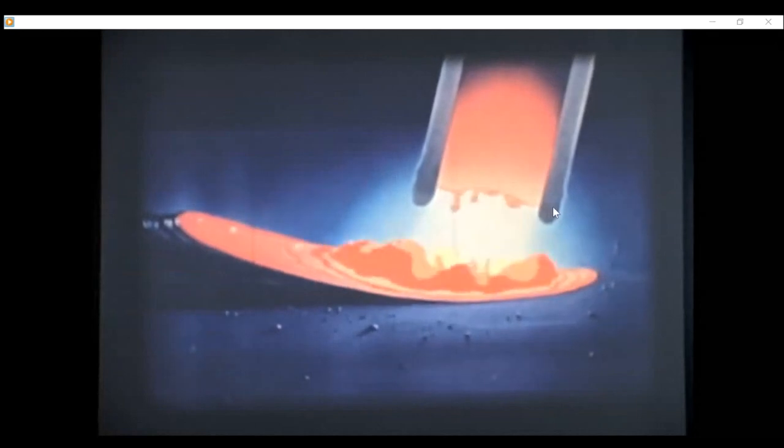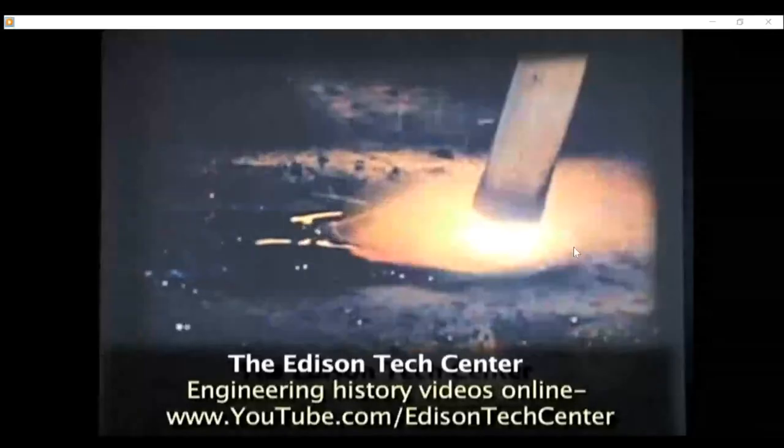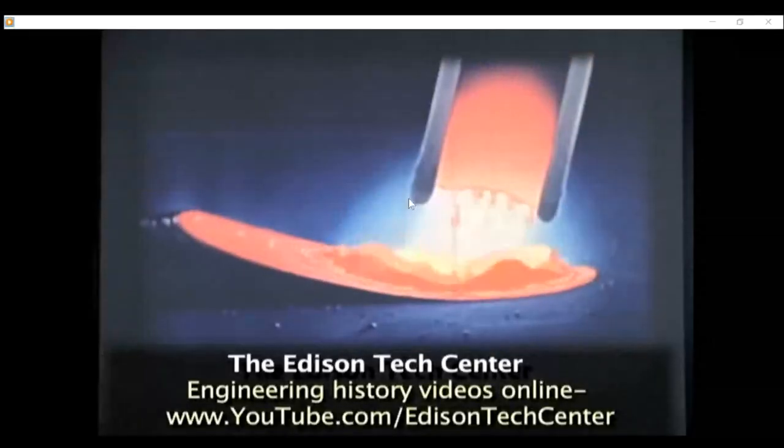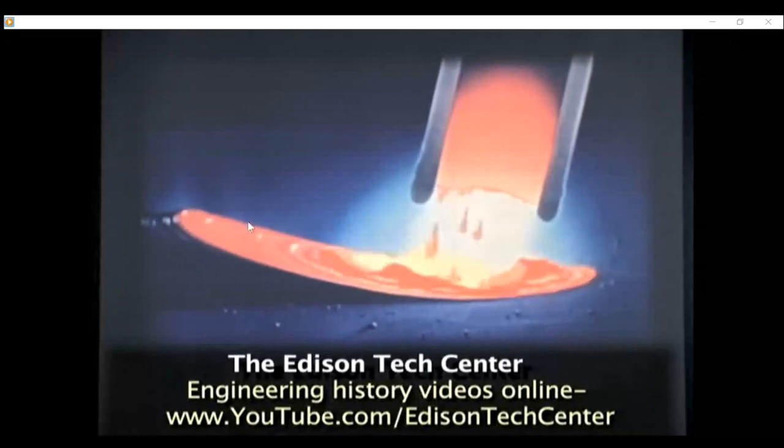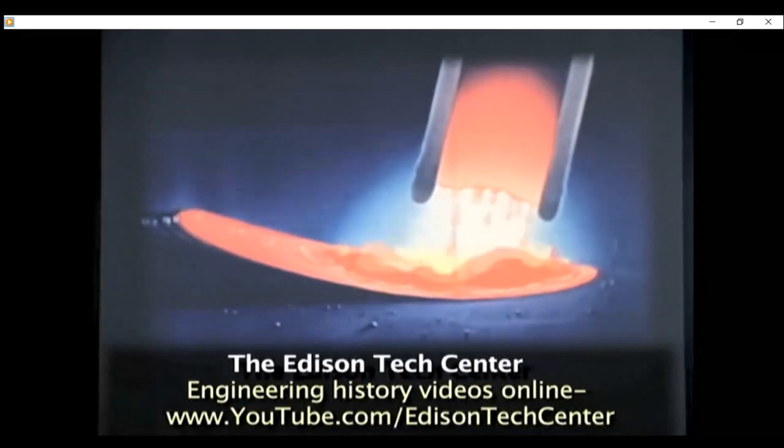This is the coating. The coating is a flux material. The coating here, guys, is a flux. This coating will also be evaporated and create gas. This gas surrounding mainly reacts with the environment to protect the weld in the electric arc welding, right?